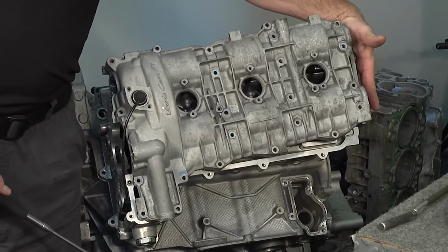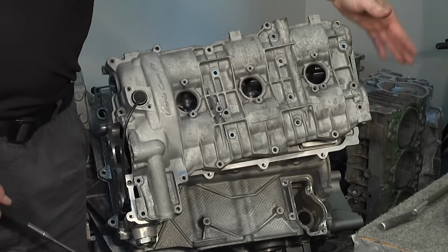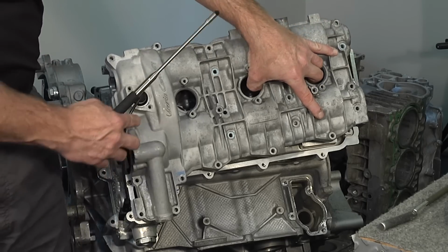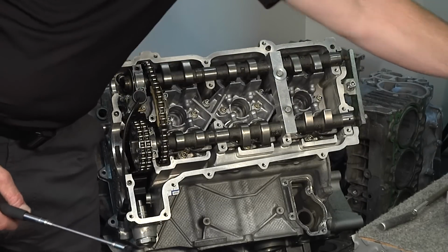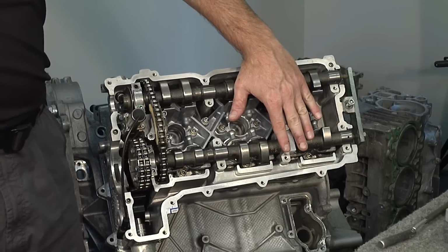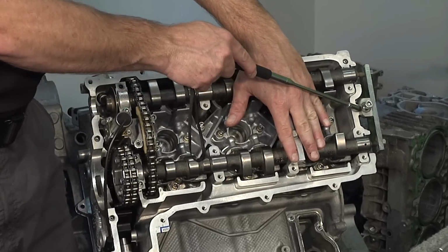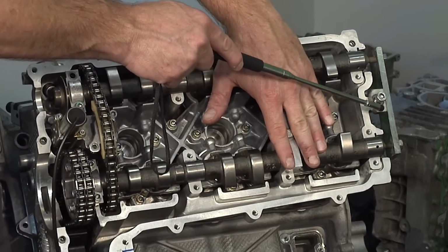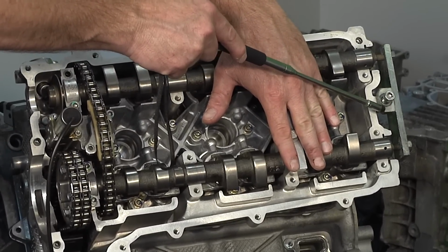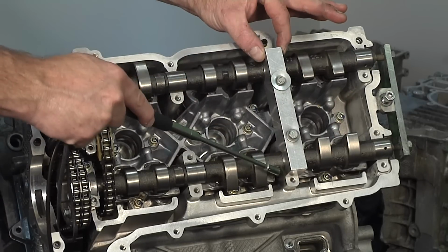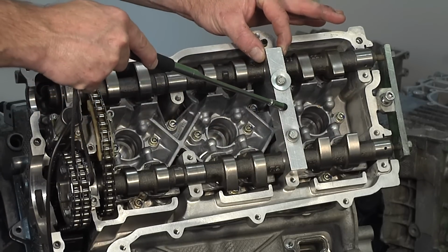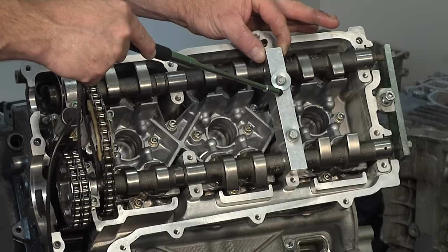You want to bolt this jig on that holds the back of your camshafts in place, because if you don't, you end up in a scenario where the cam cover is removed and there's nothing to hold your camshafts in place except for this tool that you've just put on, okay? Once that tool is in place, the cam cover is removed, and then you can fit this bridge, okay? You can't fit this bridge until the camshaft cover is removed, okay?